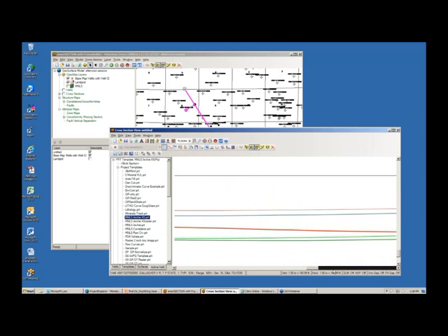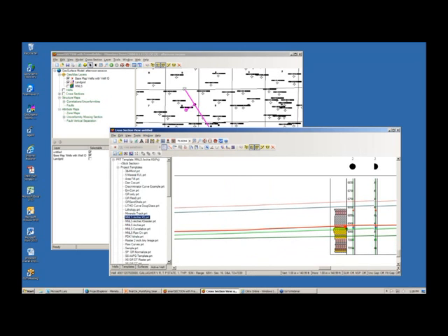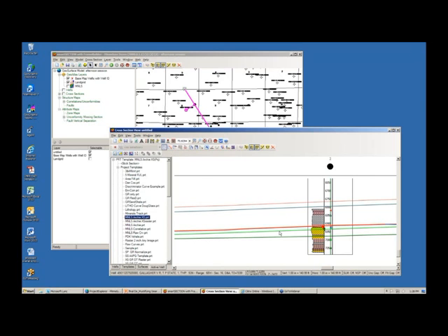Now this is a true space cross-section that's spanning a pretty large area here, so these wells are fairly far apart. But here you can go and see this particular log template that I've shown. One important thing to note is that the previous X section raster templates that you've built cannot be used in smartSECTION. So you will need to take a little bit of time to recreate some of your favorite raster log templates. But once you've got them, you're ready to work with them.